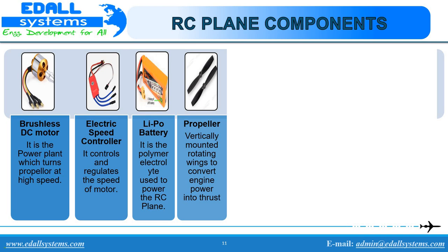Propeller. An aircraft's propellers are airfoils similar to a wing installed vertically to create thrust to drive the plane forward. Attached to the engine, they spin quickly, creating lift from the pressure differences they create, only instead of this lift causing the plane to move up, it drives the plane forward, creating thrust. This thrust and forward motion in turn causes air to pass over the wings, creating the vertical lift.